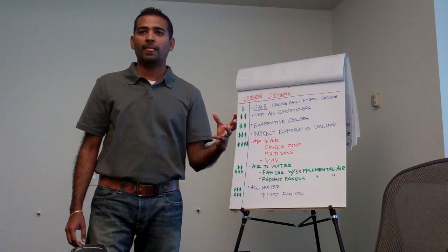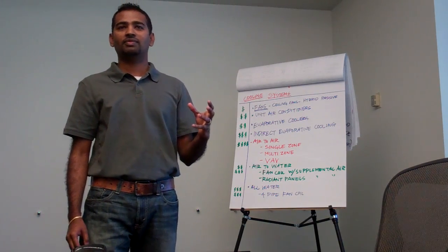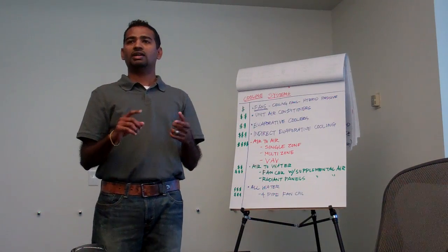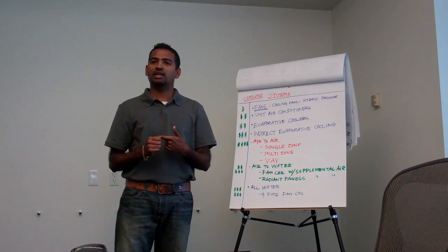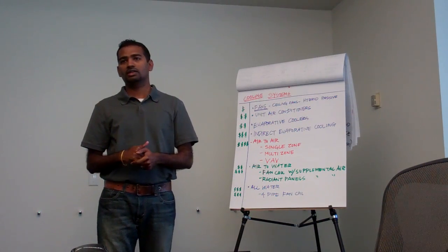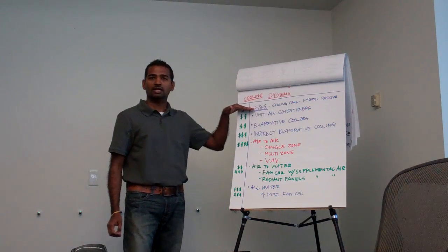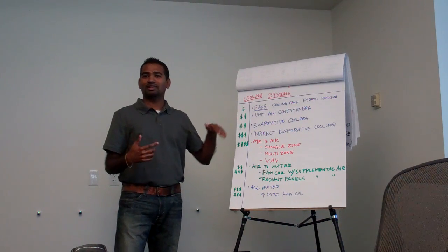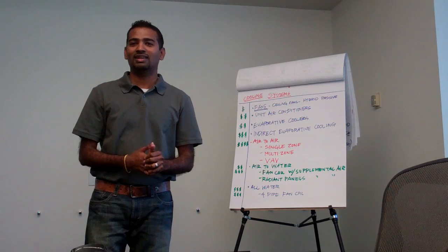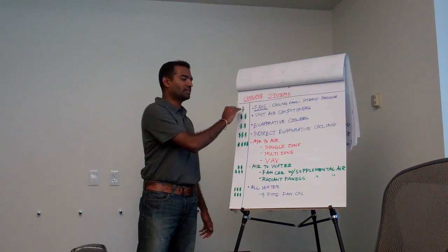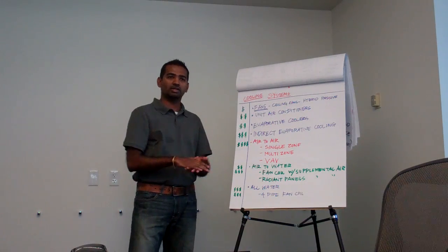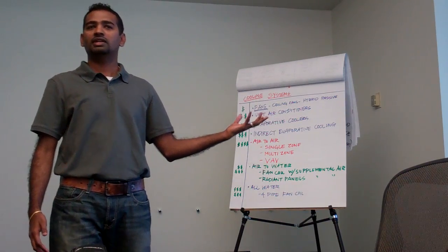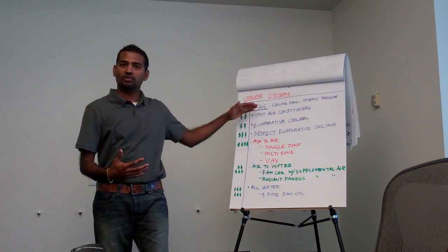How many of you remember how many feet per minute I have to move the air to increase 1 degree? 30. 50 to 30 feet per minute. If I increase that, then I can increase 1 degree in terms of comfort. But the problem with that is you keep adding 30 feet per minute, and after a while you can't stand that. Paper doesn't stay on the table, right? So you can effectively go up to 83 degrees. You can stretch the comfort zone to 83 degrees, beyond which, if the outside air temperature is 100 degrees, you still need another form of mechanical cooling.